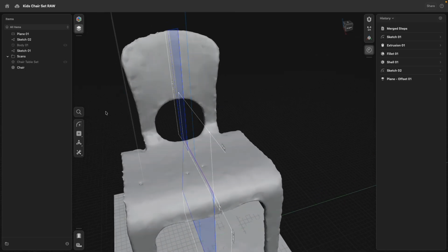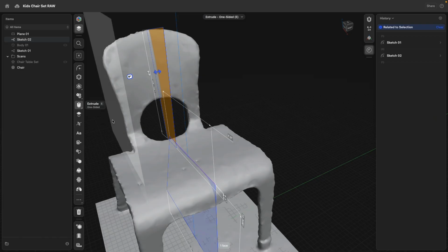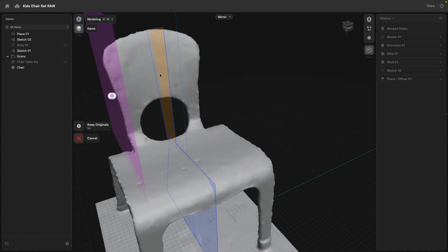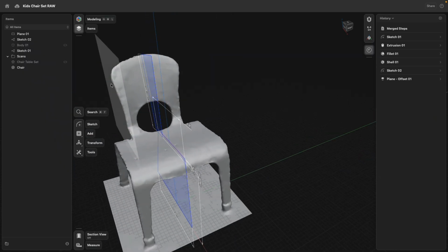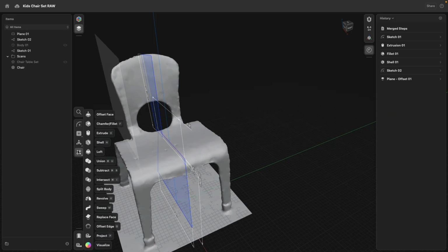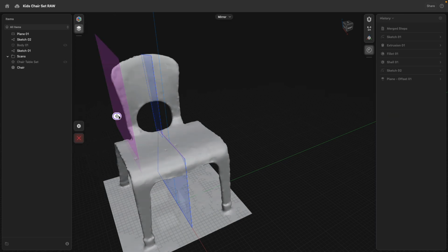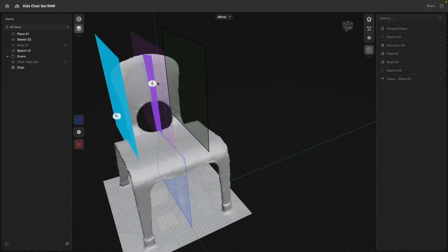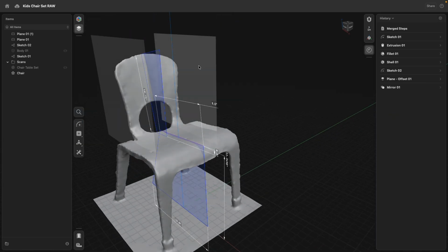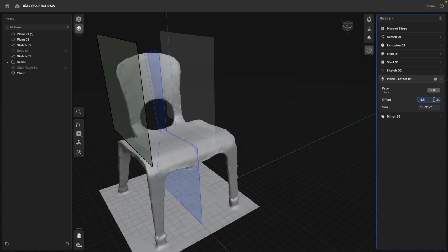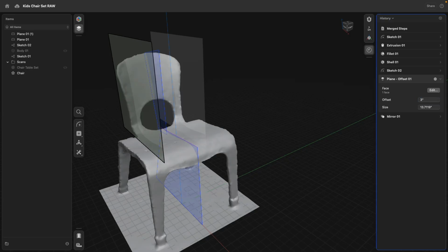4.5 inches. Very good. Maybe let's do the same, or we could select this same mirror and then click this plane. Oh no, wrong sequence. So where's the mirror command? There, this one. Oh, interesting. There. You might have to click on these icons to trigger it. So this is the object we want to mirror. This is the mirror plane. So now you see we mirrored over that other construction plane. If we change the first one, you see the second one updates.